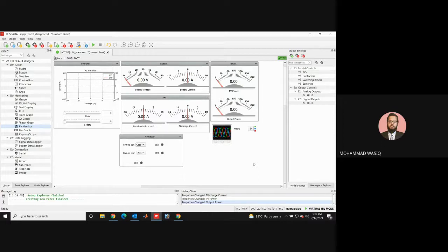Sorry, sir, to interrupt you. I just have a simple query. I thought PV cells are providing the power to charge the battery, and if the battery voltage drops below 50 or 48, the boost converter is on, and it will again start charging the battery, so the level reaches between 48 and 52. This is for only a single battery. What happens if the batteries are connected in parallel or in some way, so that one battery is charged to 51? Anything above 51, the boost converter is disabled for that battery, and for that purpose you need to apply BMS.